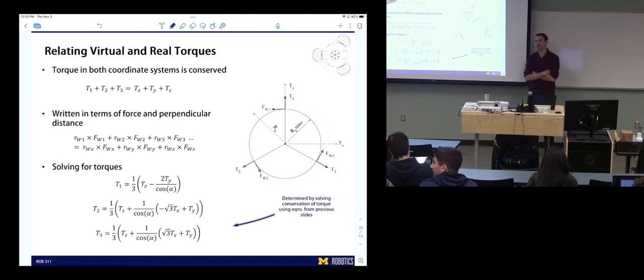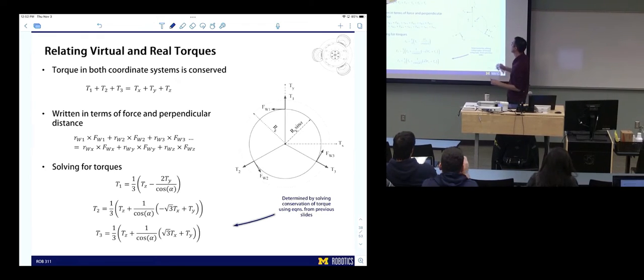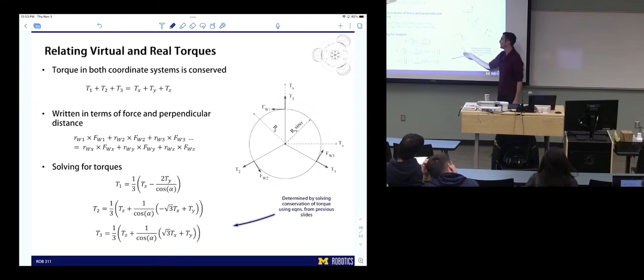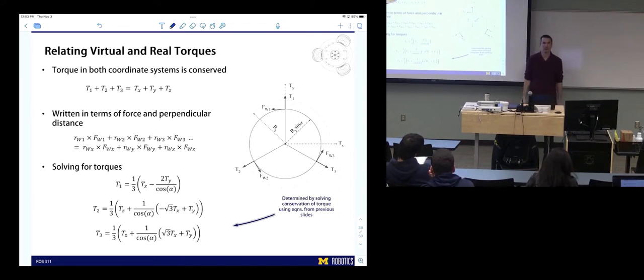It's the position of the wheels on the ball, and then the direction of their torques and forces. That's right. So what is this dashed line? That's the ball diameter circumference. Yep, that's right. And so what is this? That's the circle that the wheels are going to roll on the ball. That's right. So that's the contact circle. It's at RK sine alpha. That's RK. These are the torques and forces from the actual wheels. Awesome. You're going to need to know that.